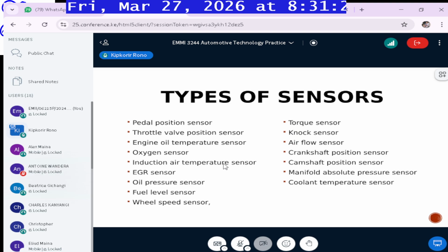Because it means that for petrol engines, for instance, if there is a very high temperature in the intake gases, pre-ignition can occur. That is, if there's a very high temperature, sometimes it can auto-ignite, especially petrol. Petrol is very volatile. Yeah. And even for diesel, they can also auto-ignite. So it's not a very good thing.